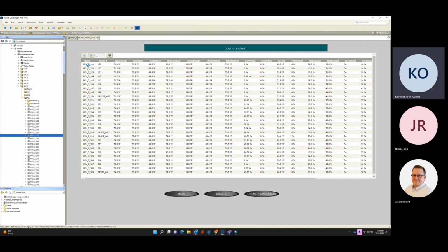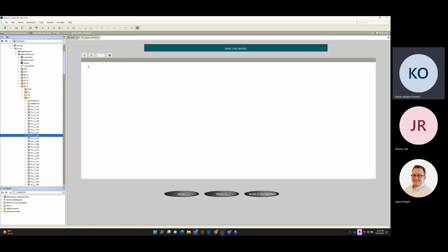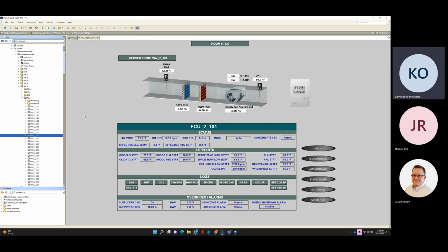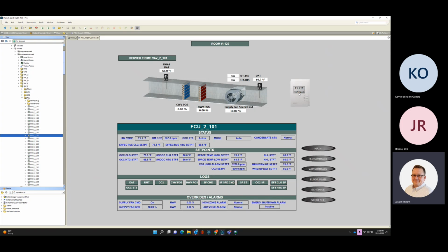Can we ask a question about the zone controls? The question was raised about the sensor, the Distech sensor on the wall. And I say Distech, I know it's not Distech brand now. So it's the sensors that you're looking at, they are temperature and CO2. Do they also have an occupancy sensor in them? They don't have an occupancy sensor, like a PIR sensor. No. But they do have this middle button that you push, and you'll see the screen say bypass.